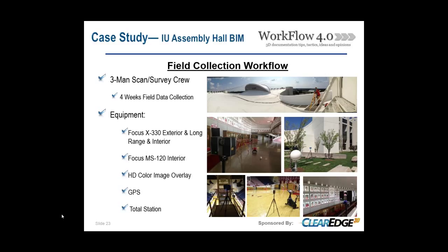In all, it took about 4 weeks to do all the field data collection, and then our staff licensed surveyor did the surveying around the entire facility. We ran a traverse around the exterior and then all the way through the interior and wrapped around the corridors, which would serve as the basis for verifying our scan registration. And then we also used that to georeference the point cloud to state plane grid and datum using GPS and total stations to do that.